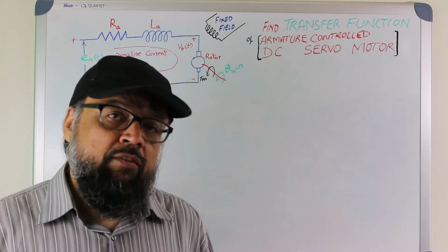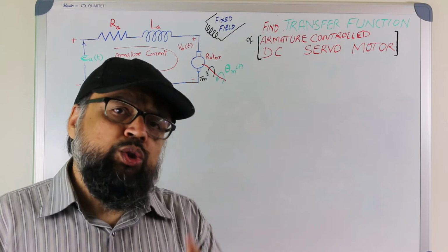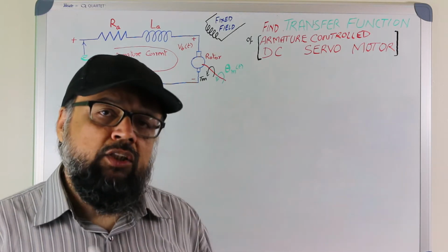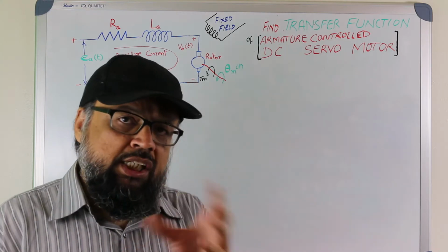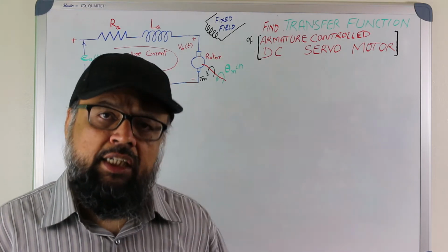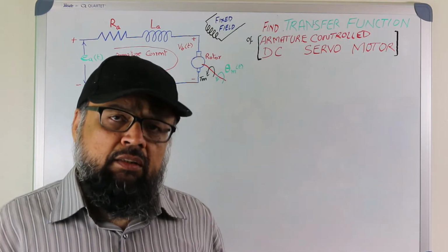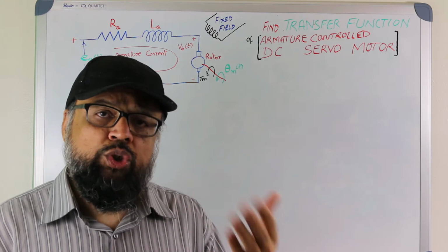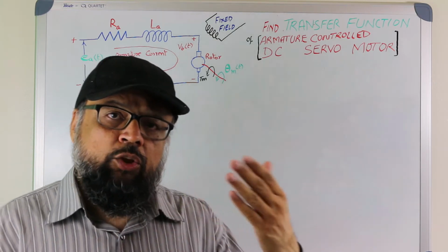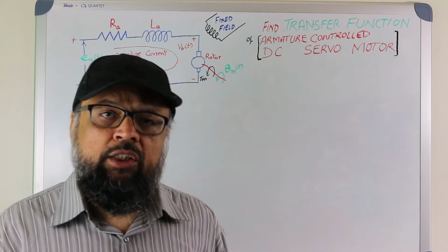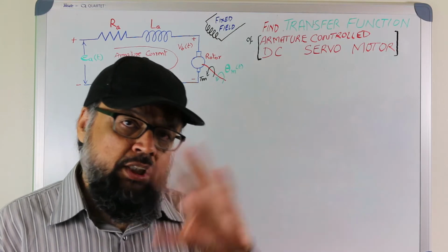And in order to do that, we have to put a sensor there, which is normally a shaft encoder. Then we use that sensor information as a feedback and try to minimize the error between the current position and the desired position. So this is a very sophisticated closed loop feedback control system. You can do many things with DC motors. You can use them for various changes in speed and changes in torque. You can put a gearbox and change the torque as well. And you can also change the direction of rotation by changing the polarity.